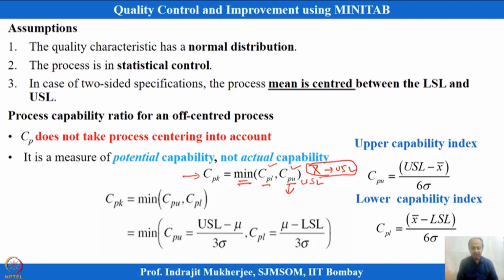So, the CPK index takes care of this centering concept of where x double bar is. Not only sigma is considered, x double bar is considered over here. The formulation is USL minus x double bar, we can think of over here, and this is x double bar, assuming that is the population average we are getting.